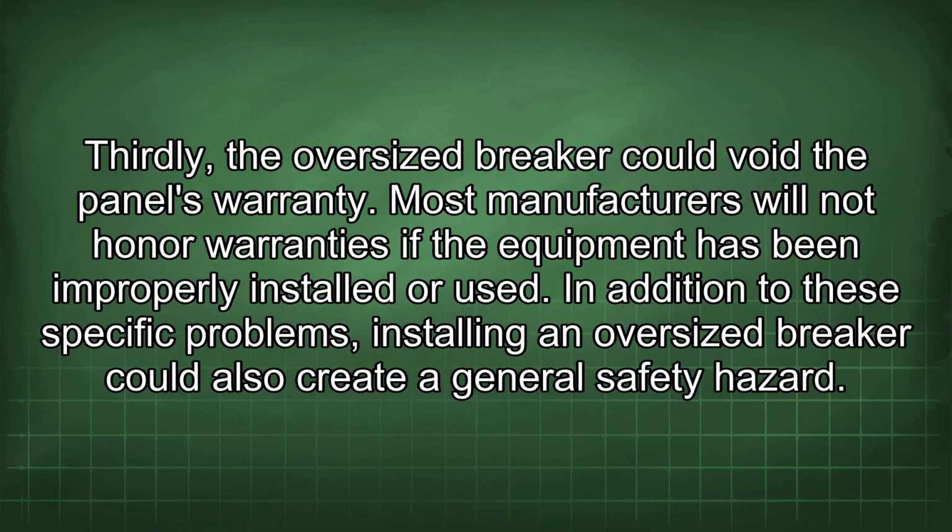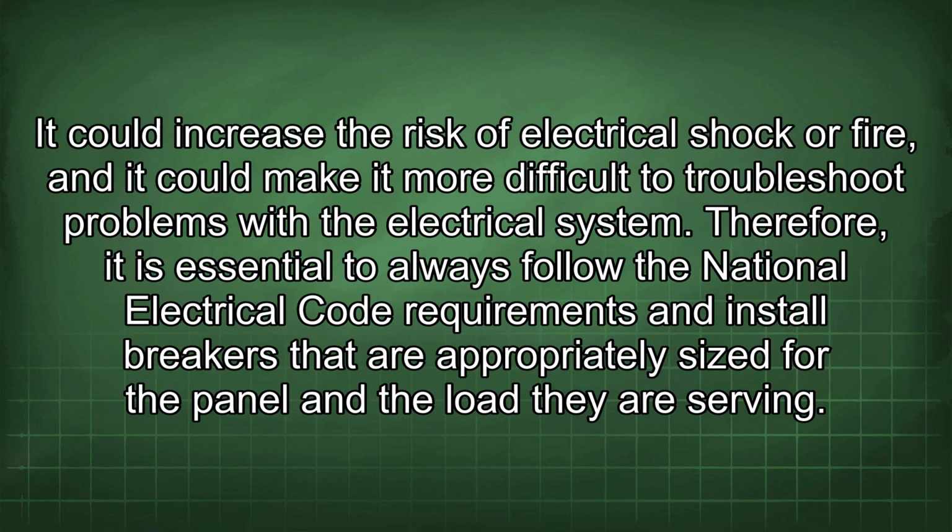In addition to these specific problems, installing an oversized breaker could also create a general safety hazard. It could increase the risk of electrical shock or fire, and it could make it more difficult to troubleshoot problems with the electrical system. Therefore, it is essential to always follow the National Electrical Code requirements and install breakers that are appropriately sized for the panel and the load they are serving.